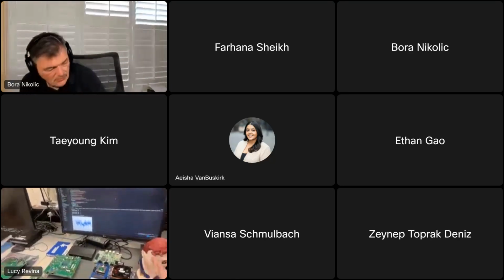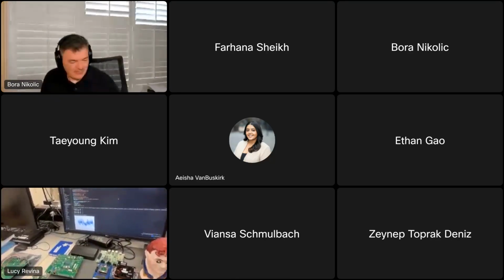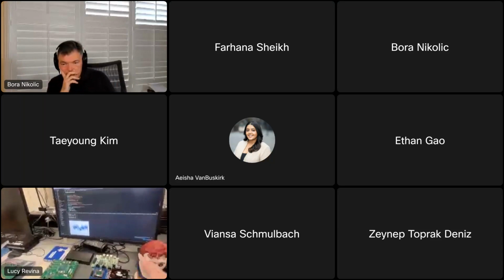And we also use this setup and also the Agilex setup right here in order to do emulation and in order to do demos that have higher LUT and memory requirements. So larger models, or sometimes we want to emulate the whole SoC. For example, it takes a few weeks to actually get the silicon back at the beginning of the bring up class. So we've been trying to develop this infrastructure with the students to make this process easier.